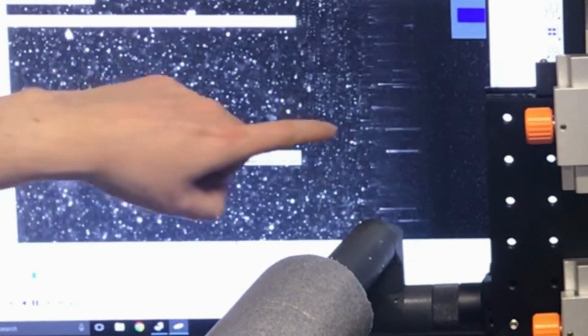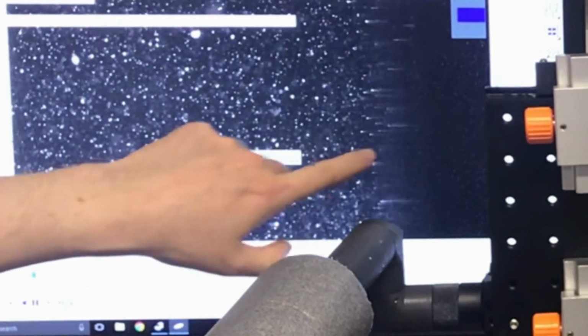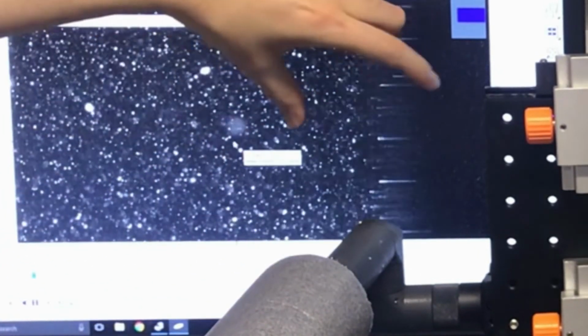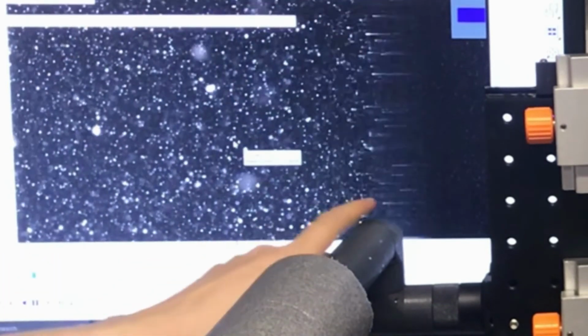So you can see the particles making their way up here, and we've got this blurring occurring near to the surface, and those striations, or the elongation there, is very characteristic of refraction occurring near to the surface. So it doesn't take much at all for this to occur. So that's our raw PIV data, and what we would now do is run this through various filters and through the PIV algorithm to return a set of velocity vectors from this raw data.